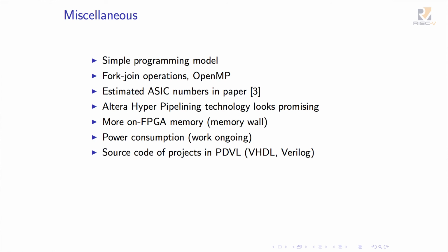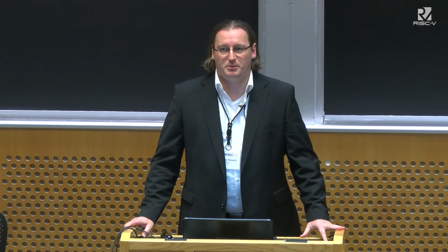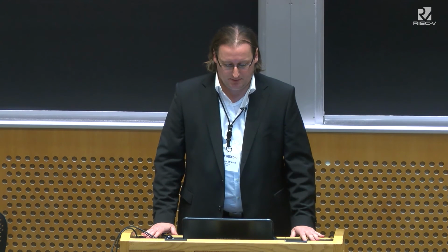So finally, this is a programming model. It's very simple for this. You can easily program fork join operations, and you can add OpenMP here. I have estimated ASIC numbers in one of my papers. The hyperpipelining methodology of Altera looks very promising. Yet again, I would like to say that FPGAs need more memories on chip.